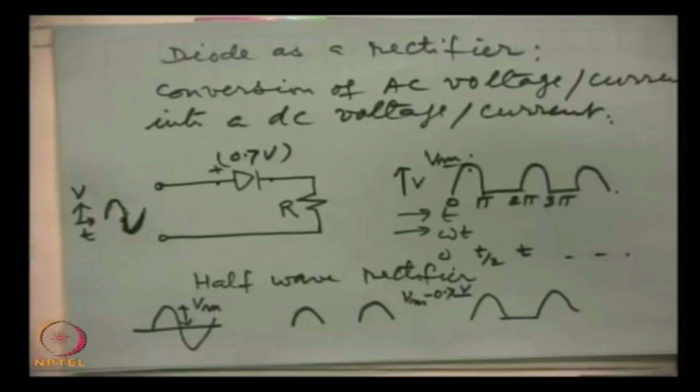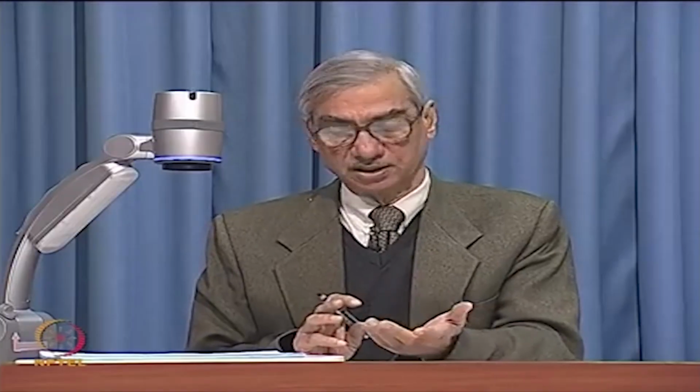They will not require any further rectification, but most of the devices like at home what we use, music systems, transistors, cassette recorders, tape recorders, television or computer, they all require a DC source, and the power we supply is from mains. So, we have to use a rectifier, and before that we have to use a step down transformer, because these circuits will be actually rectifying smaller voltages, say from 5 volts to 30 or 50 volts.